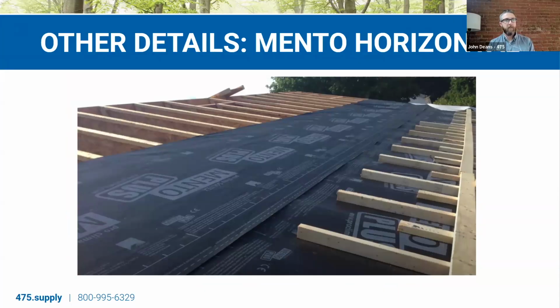Both of those case studies had the membrane running up the slope. So this is a view of if you do it horizontally. Basically they're doing this in a stepwise fashion. They're laying the membrane down and then putting shorter battens on there and then what looks like horizontal 2x to basically be able to walk around on it and hold material up there and whatnot.